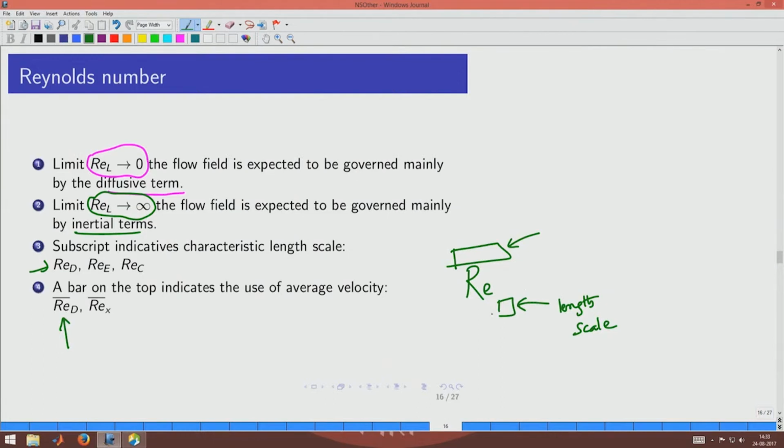Okay. So, do pay attention, and the way the Reynolds number is defined could be different if any of these two are different. So, do not compare an expression which is written like this and written like this. Okay. So, these two can be very different. So, pay attention, and if it is looking different at the subscript, then look at how it has been defined, and it could just mean that the way we define the Reynolds number may be explaining the differences that we see in the expressions. And we will come to some of these nuances when we come to the friction factor discussions.